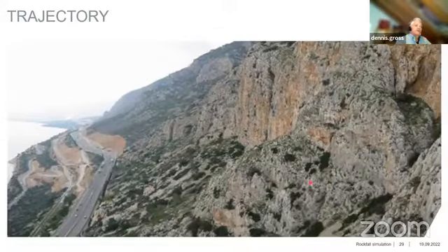So here, this is actually to illustrate what the difficulties are, and I will come back to that again and again, to determine the trajectory. Because until very lately, what we usually did would have been 2D rockfall simulations, and it's only in the last, I would say, 5, 6 years that it gets more and more common that we carry out 3D rockfall simulations to have a better understanding of the trajectory and how the rock will move on the slopes, taking into account the topography of the slope.